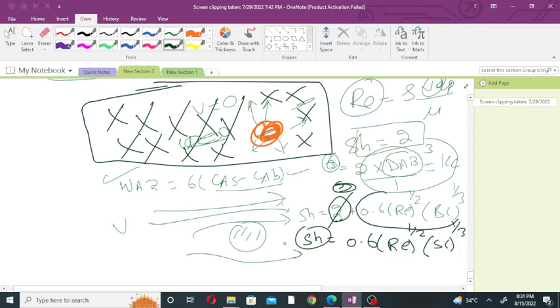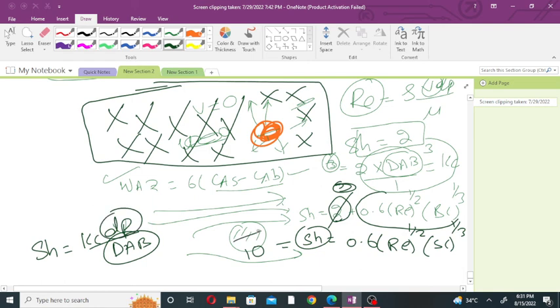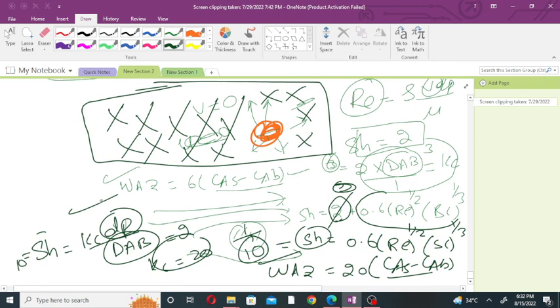Once you determine the Sherwood number, suppose Sherwood number is 10, then Sherwood number is nothing but Kc times the diameter of the particle divided by DAB. The DAB is given to us, and the diameter of the particle is usually given, suppose it is 1 centimeter, and suppose diffusivity is 2. With Sherwood number 10, 10 multiplied by 2 is 20, divided by 1, so Kc will be equal to 20. Put this in the mass transfer equation, and you will get 20 into the concentration gradient, so you will get the flux. So this was just an introduction to mass transfer correlations.